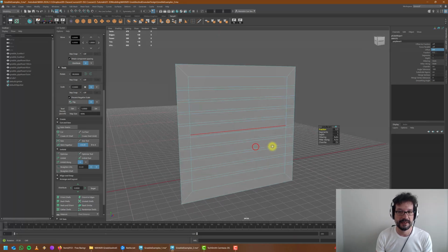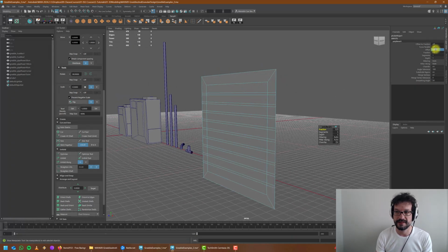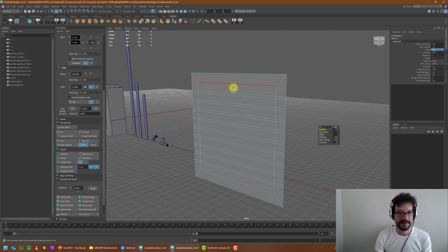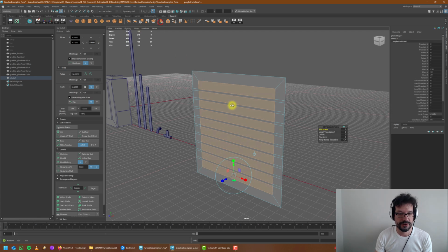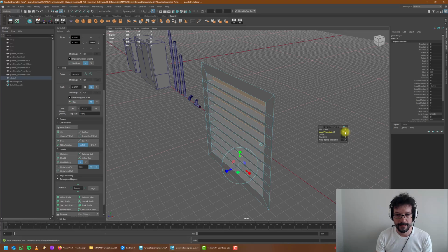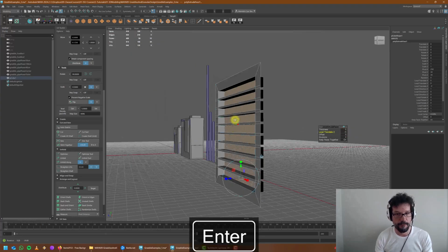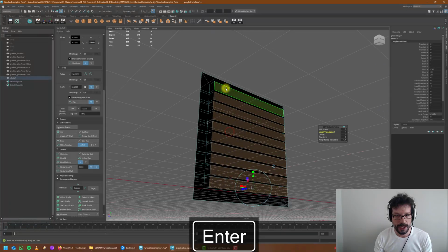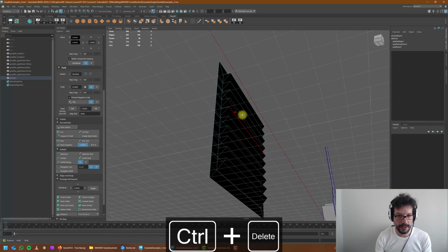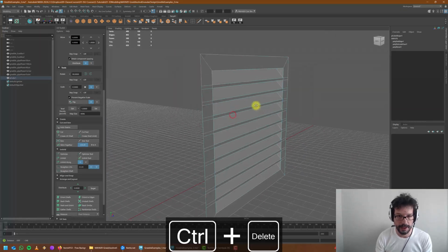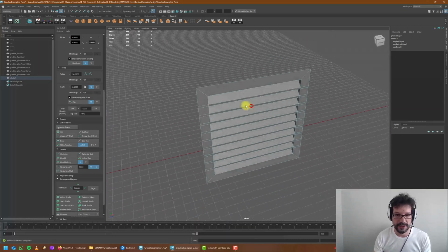okay, and then you can decide on poly bevel size. For example, right now it is 0.5 centimeter. The offset is 0.5 centimeter. Okay, that's perfectly fine. So I can grab all of these faces, extrude them like so, -4. I don't know, I'm making stuff up. And then grab the underside edges, and when I say Control Delete, ta-da! Okay, nice looking geometry.